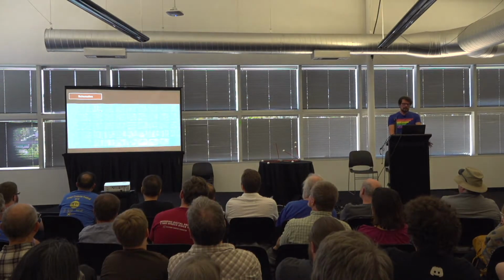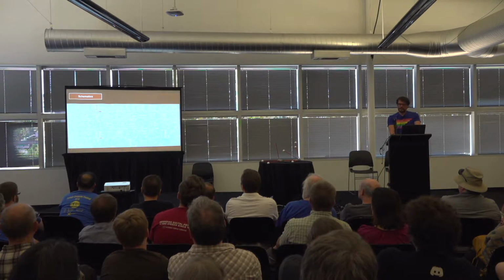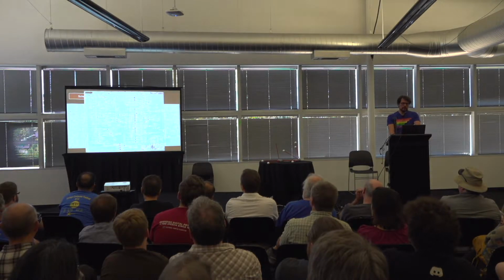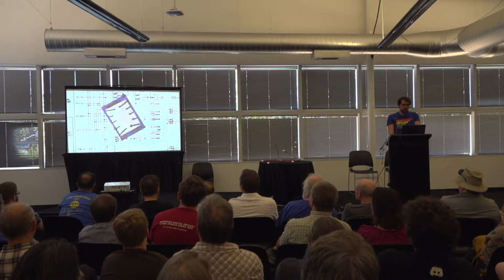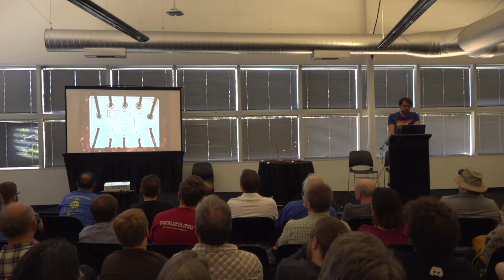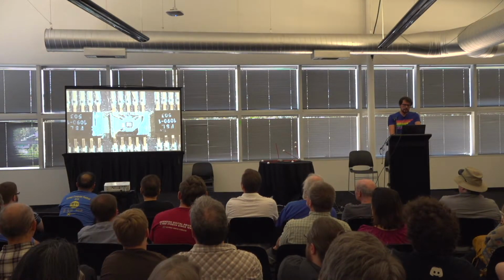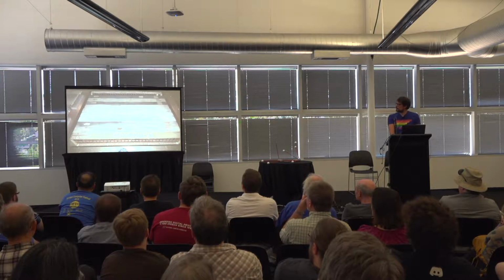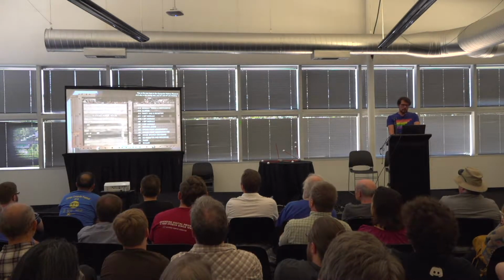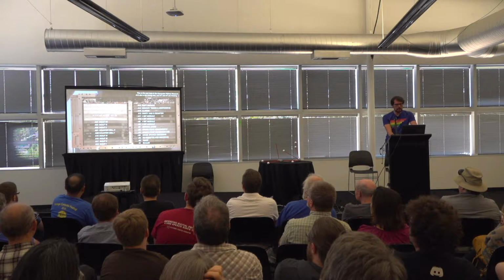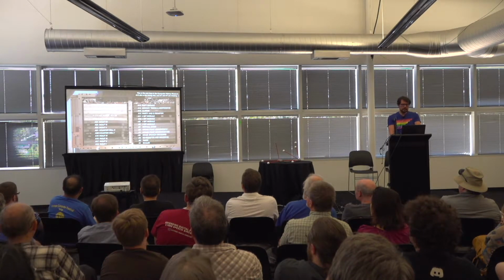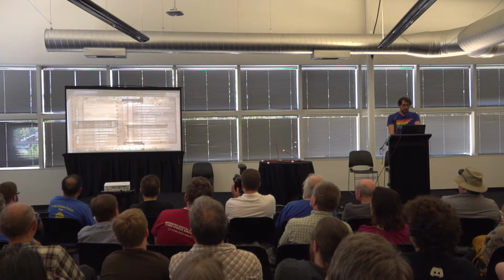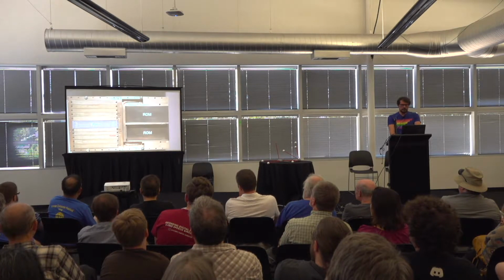The complete schematics are publicly available and fit on just 49 sheets. The whole implementation uses a single type of gate, a 3-input NOR gate. 2 of these are contained in one integrated circuit, and about 100 of these ICs form a logic module. 24 logic modules and some interface and power supply modules are connected together in tray A, which also contains the I/O and debug connectors. Tray B contains various driver and amplifier modules, as well as RAM and ROM.